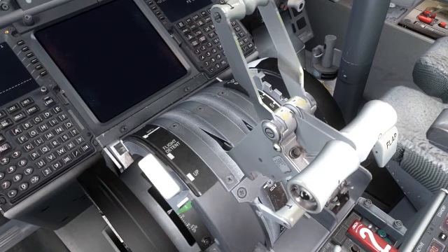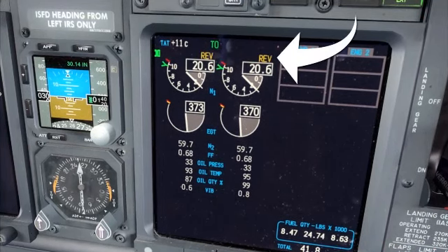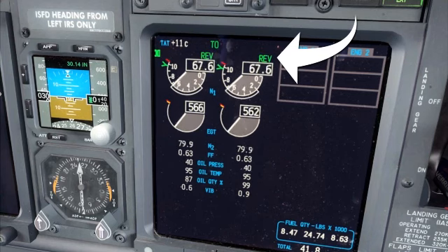Only 2 detents, maximum and idle, are selectable in your PMDG 737NGX, as opposed to its real-world counterpart that has the normal detent in addition. When the reverser sleeves move from their stowed position, a cockpit amber reverse alert illuminates. When the reverser fully reaches its deployed position, the reverse alert turns green and the reverse thrust lever can be pulled aft of the idle reverse thrust detent.